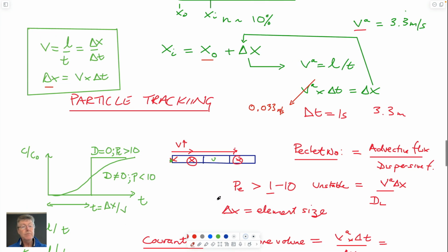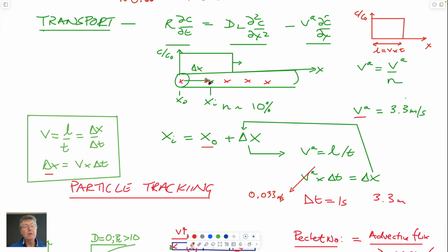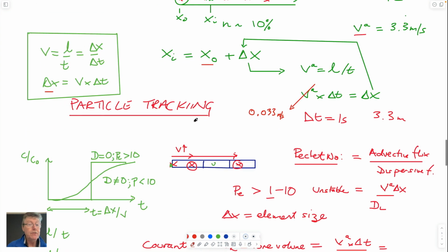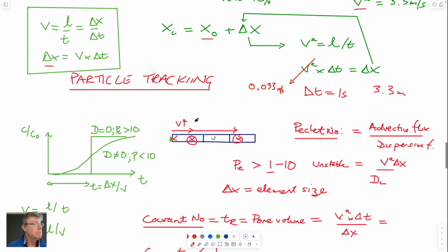And so all we need to do is we release a particle at this source, at the upstream location, we allow it to go downstream, then we release another particle at the next time step, and we see how they all move downstream. We can calculate within each box or bucket that they arrive from the number of particles what the concentration would be, because each of those particles represents a released mass of contaminant which is sent from the upstream location. And if we do that, we can essentially replicate what these models do. And that's all these models do.